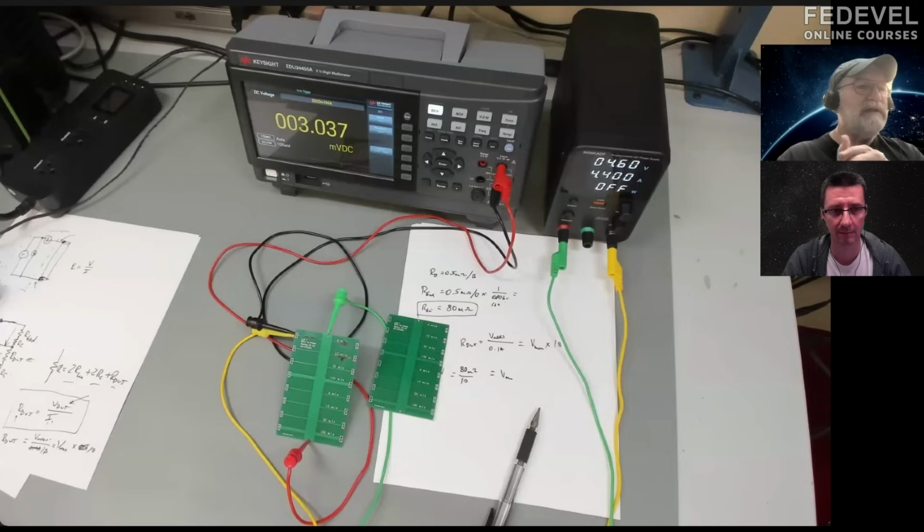And that's where tools like the ANSYS tool, Hyperlynx, and ADS have 3D simulators to calculate what that current distribution is and what the IR drops are in all the different locations. When you get in that 100 amp range for a single device, those tools are essential to give you confidence. I refer to it as building a virtual prototype. Before you build the real prototype, you build a virtual prototype, and you can do design trade-offs and design analysis so much faster in a virtual prototype than a real one. So you've got to use a virtual prototype to do that kind of analysis.